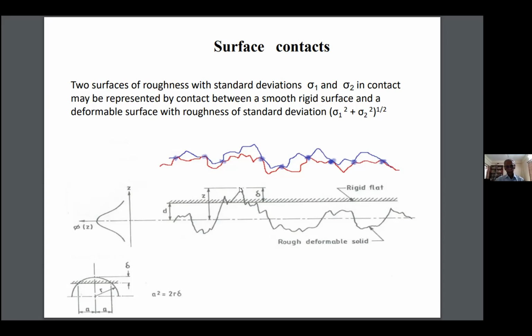If you look at a real image of a surface, either in a scanning electron microscope or some other, you will see that the surfaces are never like this. This is what is shown in a Talysurf or some other surface roughness measurement machine, but the surfaces never have peaks like this. They are more like this.